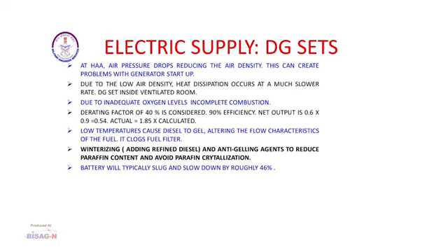Electric supply. In Leh area, the majority of the area is still dependent on standby supply through DG sets, or even for the primary supply through DG sets. At high altitude areas, since the air pressure is low, sufficient air is not there to mix with the diesel and there are startup problems due to this. Due to low density at HAA, heat dissipation is also very less.